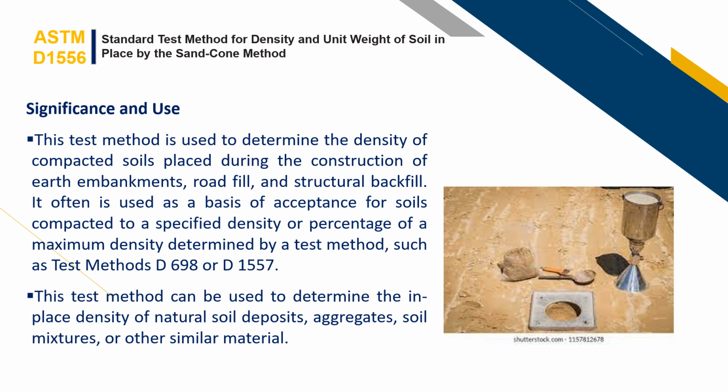It is often used as a basis of acceptance for soils compacted to a specified density or percentage of a maximum density determined by test methods such as test methods D698 or D1557. This test method can also be used to determine the in-place density of natural soil deposits, aggregates, soil mixtures, or other similar materials.